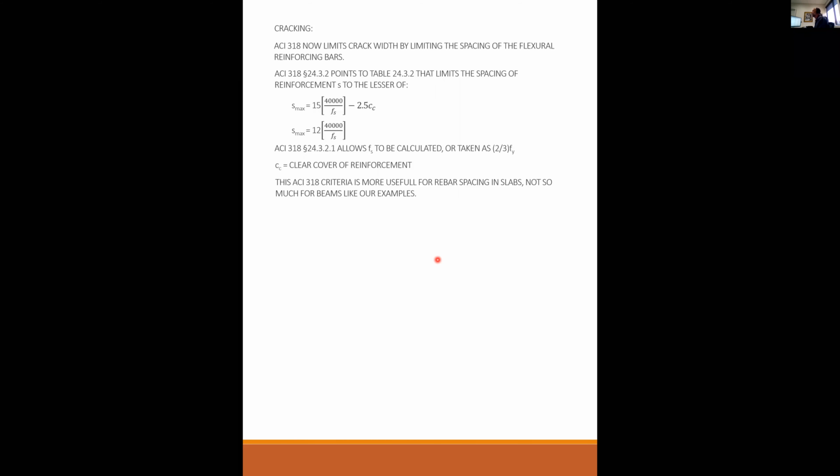I'm using 3 number 10s or 3 number 9s or whatever. And you didn't do the minimum steel check. You didn't do the maximum steel check. You didn't do the most important check, phi Mn greater than Mu. Okay, so that's the first observation. Any questions on that?